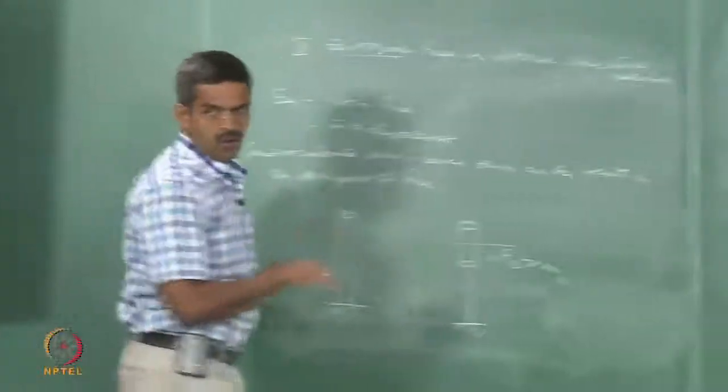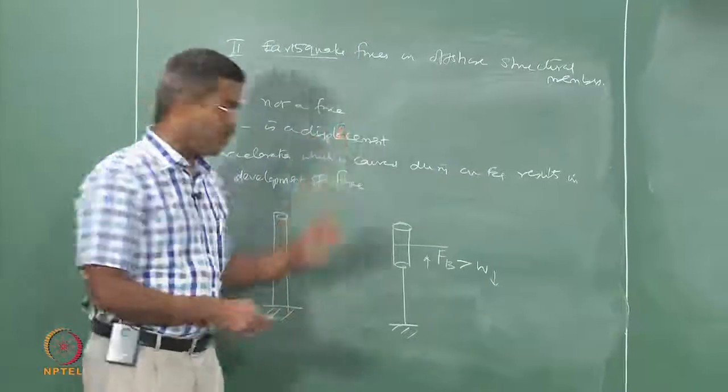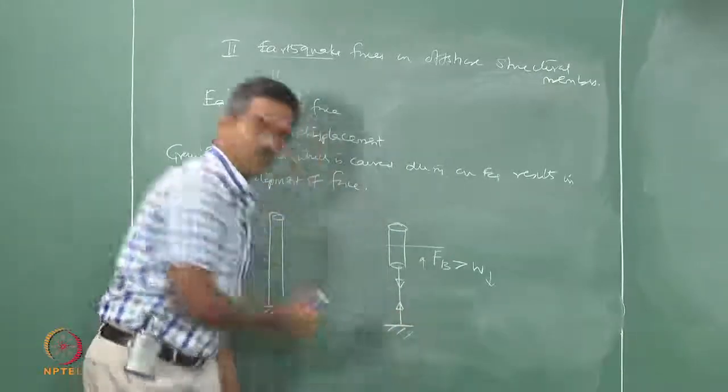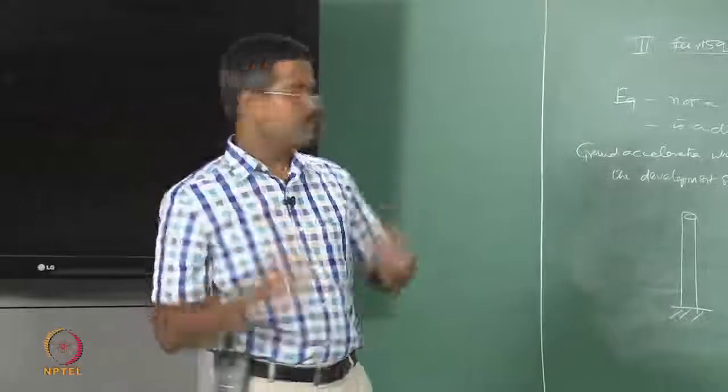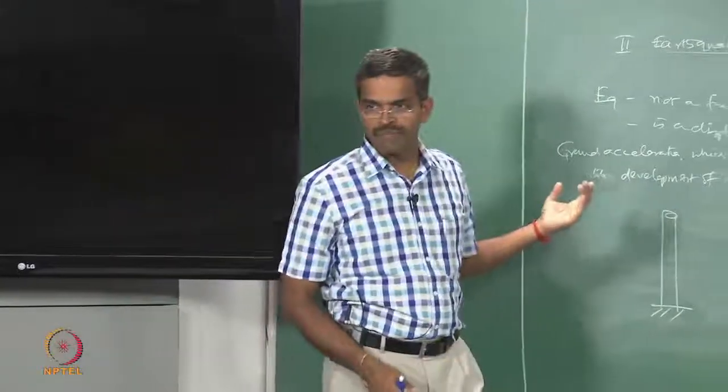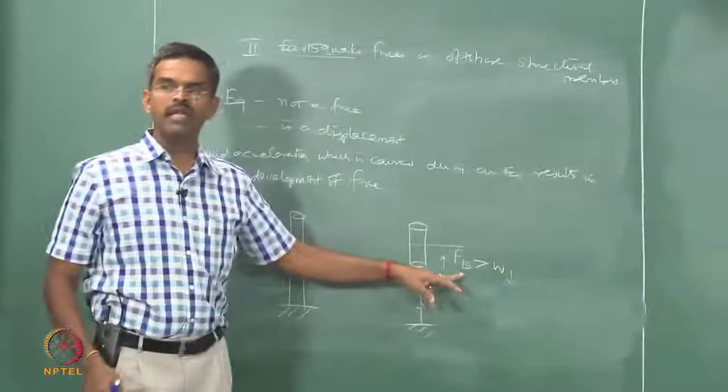Since the weight is very low and the body is being pushed up all the time, we always need a cable which is in tension to pull this body down, otherwise the body cannot be held in position, the body will get afloat, body will be thrown out from the medium, because the buoyancy force is extraordinarily high compared to W.